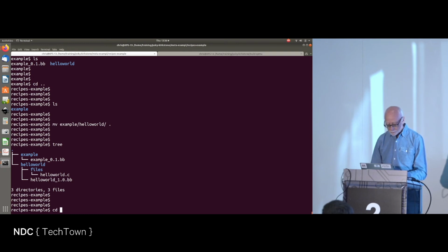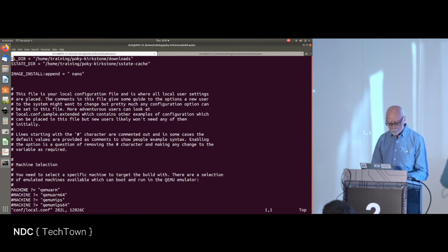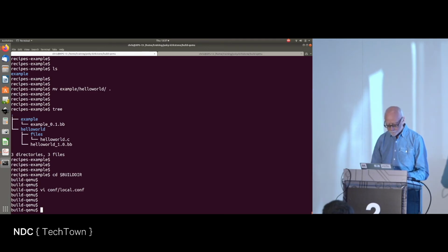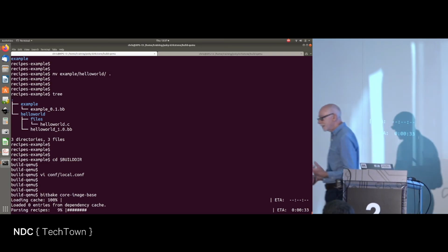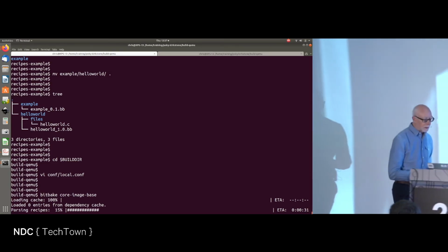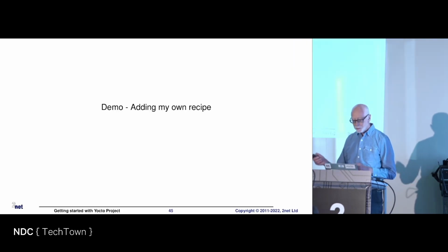Okay, so cd $BUILD here. Go into conf, local.conf, and then head down here. And then do a bitbake. Okay, and that is now going to pick up my recipe, I hope, and add a hello world program to my target. Come back to that in a moment or two.